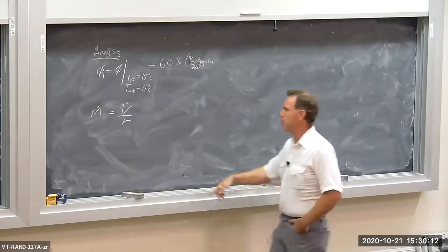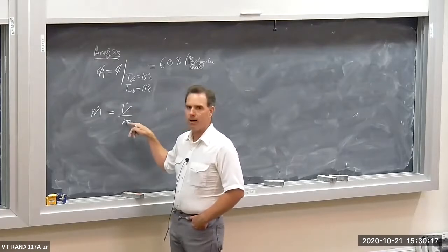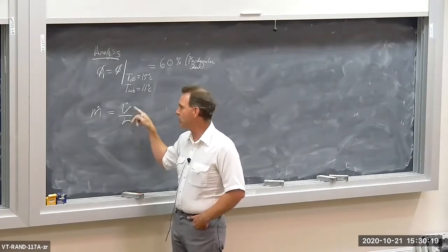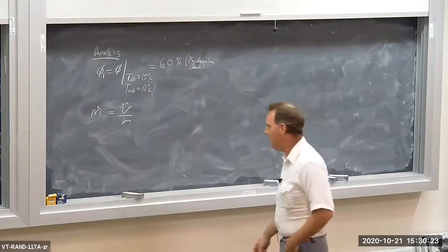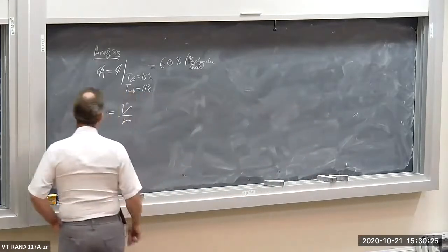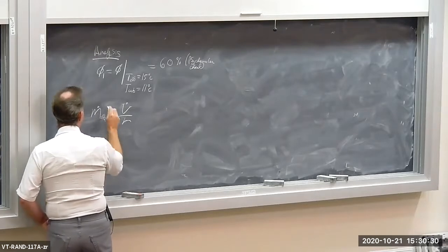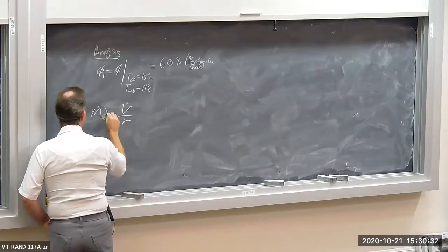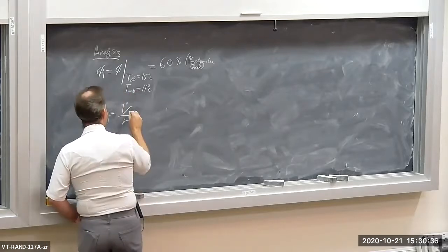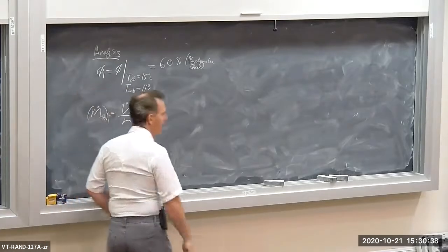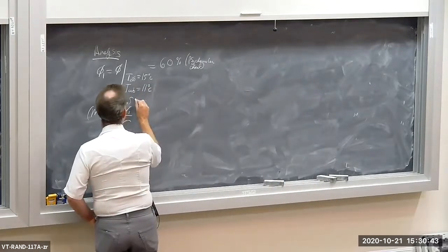So the volume per second divided by volume per mass gives you kilograms per second, or kilograms per unit time. I only want the dry air component, at the inlet, so this is dry air at location 1. And that means I want the volume flow rate at the inlet, and this is the volume flow rate for the mixture. So remember, this is for the mix.